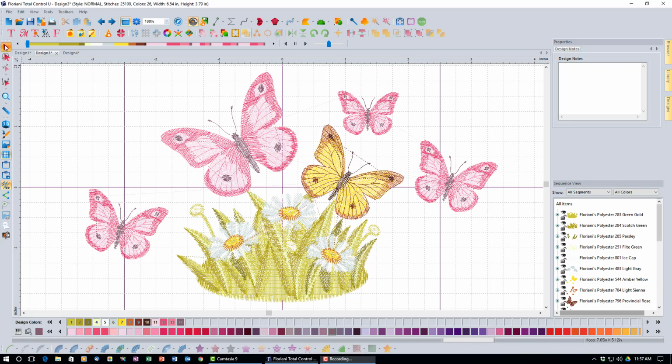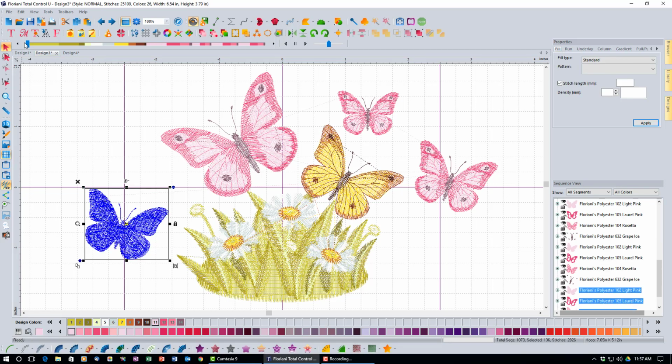So let me go back to normal select mode, and this is our slow redraw tool right here, and this is the icon that basically turns it on and off. Now by default, it's here all the time. If you would prefer not to see it, if you want just a little bit more screen real estate, you can turn that off, but I just usually leave mine on all the time. So this toggles the slow redraw on and off. It doesn't go back and forth between slow redrawing and not slow redrawing. You get out of slow redrawing by selecting your normal select tool.